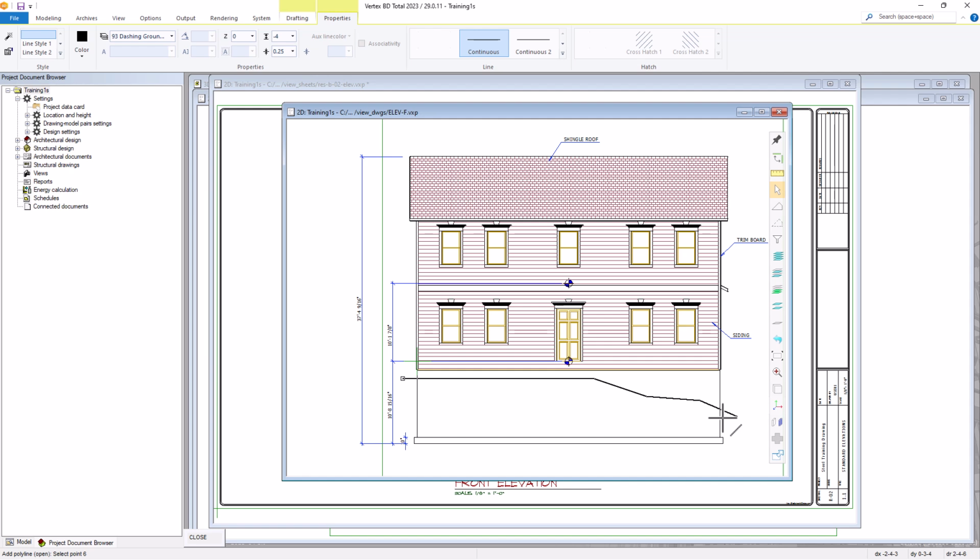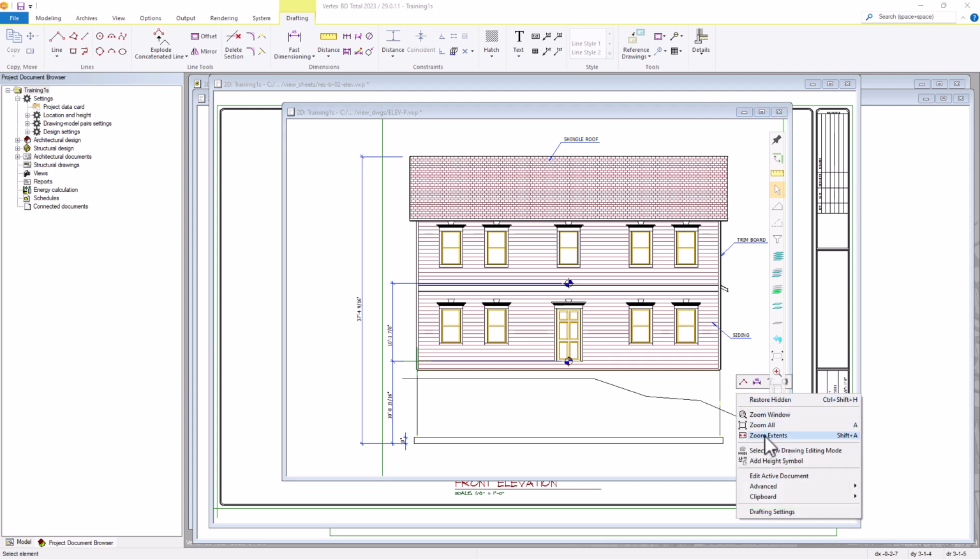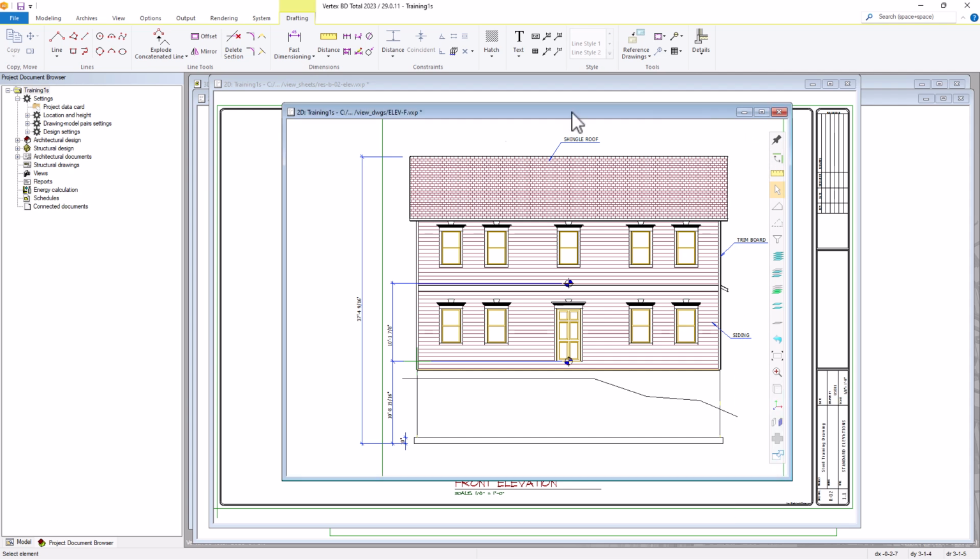So anything below that line, these basement foundation walls, will be shown in a dashed line, and everything above it will be in a solid line. So we'll hit V to confirm, hit Escape, we'll hit Close Out, or hit Save.